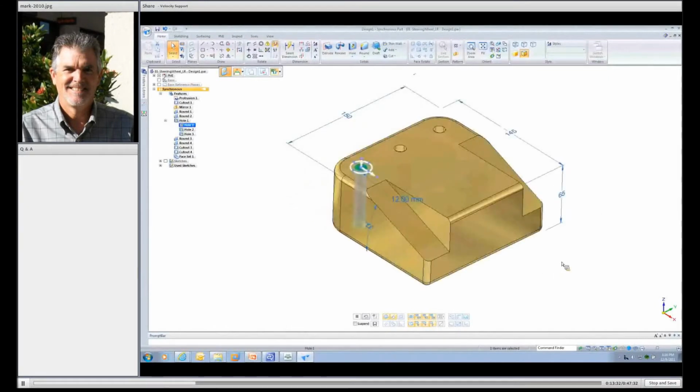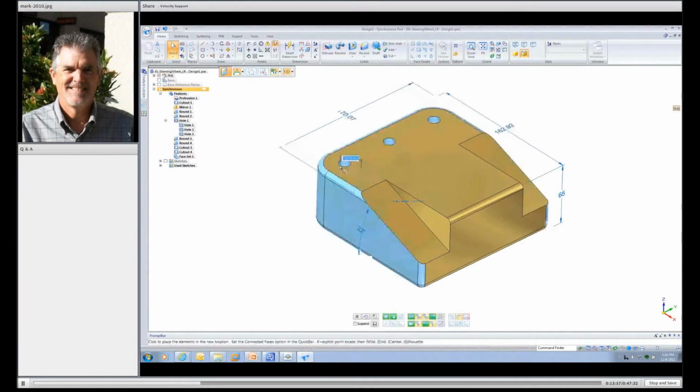And you'll notice, again, that's one of the default ones that we turn on for you. Now, when I move this particular model, everything appears to be moving as it should with the design intent that I initially had. So the sides and back faces are going to stay perpendicular to, or parallel to, the base coordinate system. So in this case, I can just move it out and I can click to place.